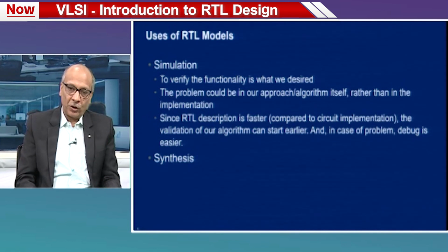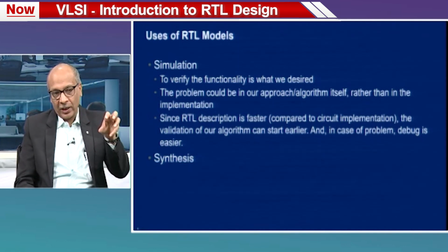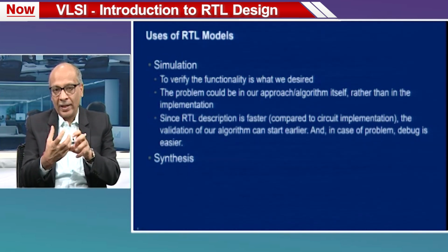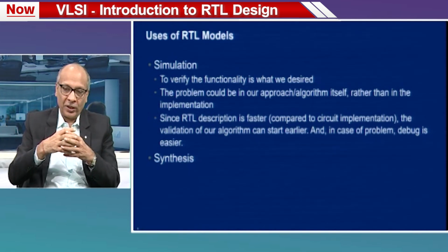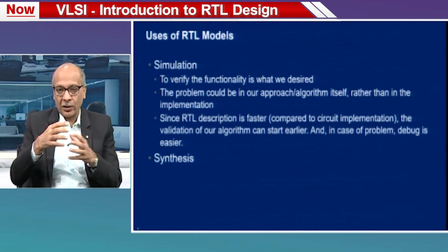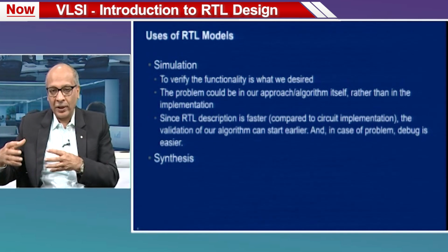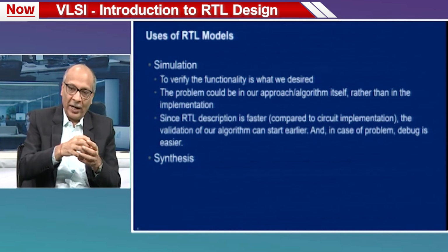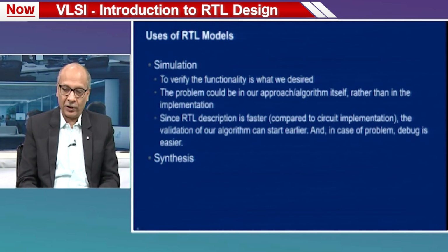The other major usage of RTL model is synthesis. What synthesis means is you have an RTL description, you take it through a tool called a synthesis tool, and at the output you get a gate level realization. For example, you could say count is equal to count plus 1, which is a counter, and when you send this to a synthesis tool, at the output you will get the D flip flop, the JK flip flop, the logic which is required to realize the counter, things that you would have usually done through your K-map kind of circuit design.